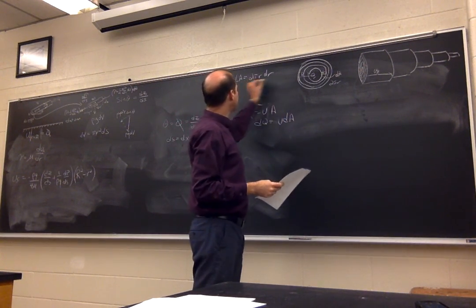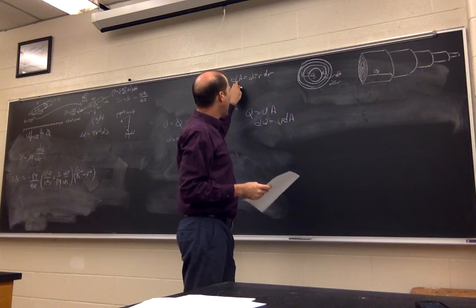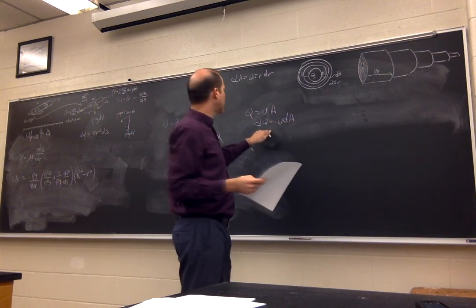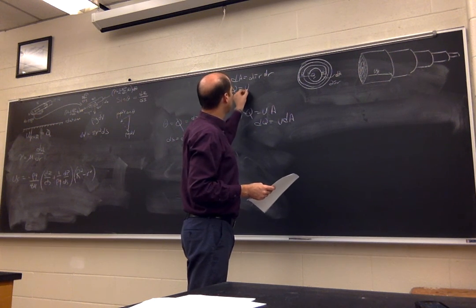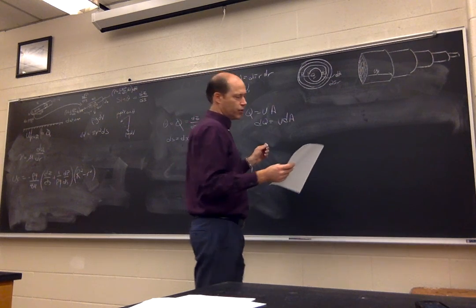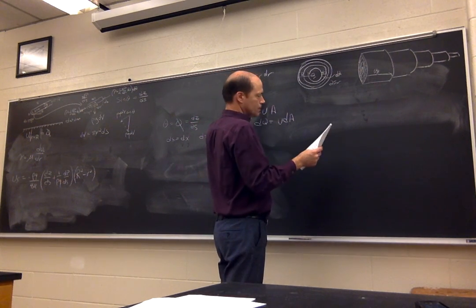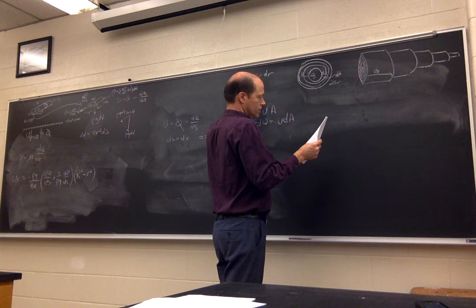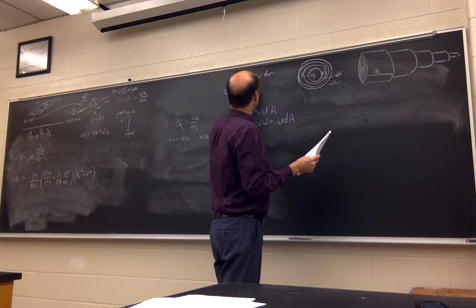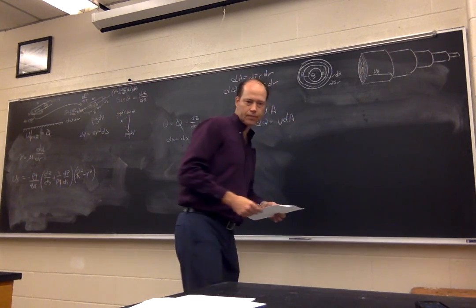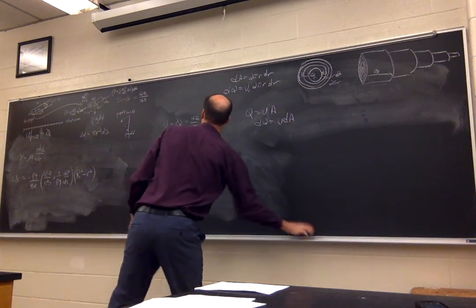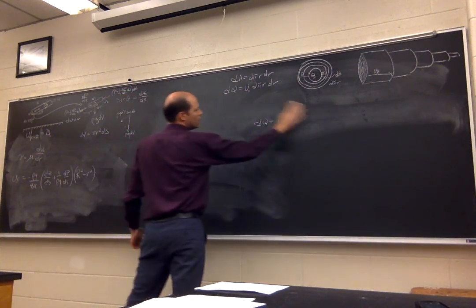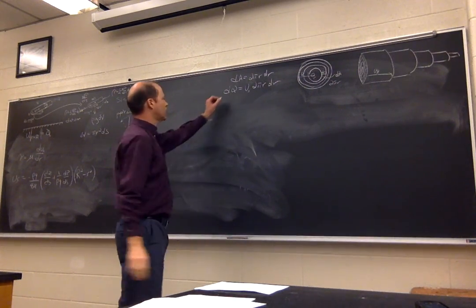So now we can take that definition of dA and put it in here for our discharge, such that dq is equal to the velocity profile, I should put in the x direction because that's the way we're looking at this, times 2 pi little r dr. So that gets us a definition of dq.